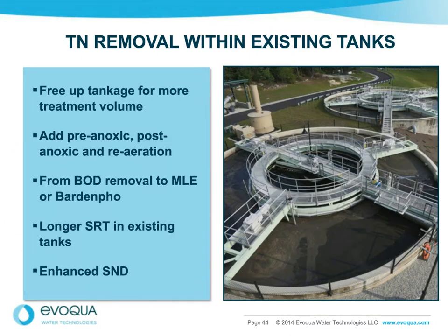Another case study is freeing up tankage, as I mentioned earlier. This was a facility that had a package-style donut shape extended aeration process. They were going to get a nitrification and a phosphorus limit and needed to double its capacity. Using existing tankage and existing clarifiers, they added new aeration to increase the aeration capacity, a very tight footprint and very economical. They achieved this using an existing footprint, and ultimately ended up achieving a higher level of effluent quality than what they were really trying to do at no additional cost, because we were able to drive what's called simultaneous nitrification-denitrification.